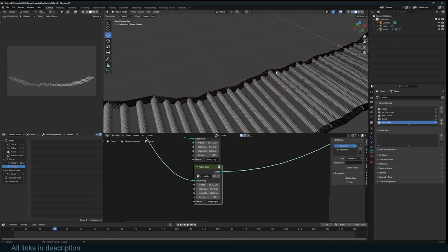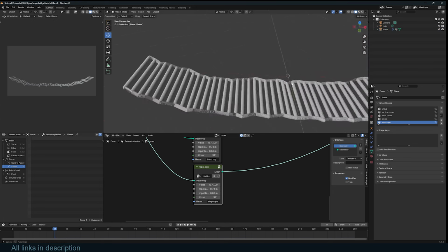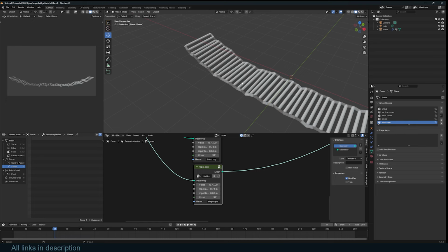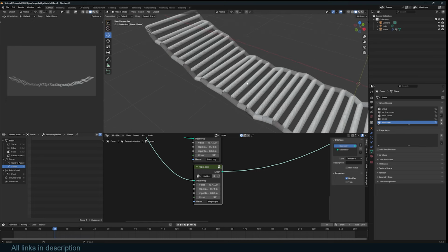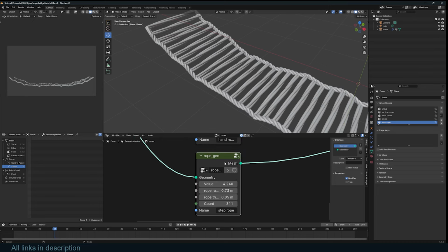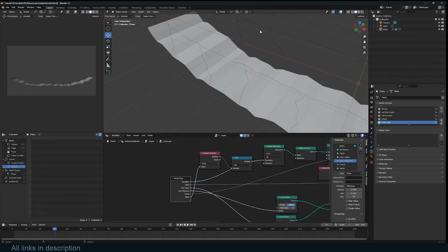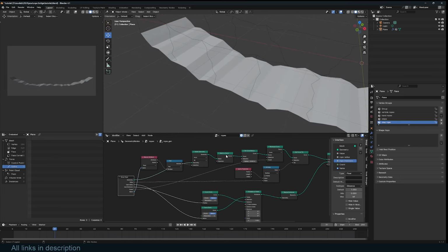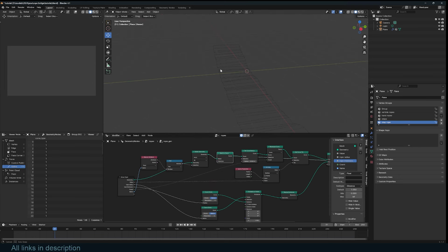This time we're going to copy just the step rope. And if you look at this, we run into a problem, because this vertex group also includes the vertices connecting on the X, so these vertices are also getting selected. Let me first reduce the turns, enter this group, and make sure that I'm only selecting the edges, because right now this is what we have. I only want the edges here.